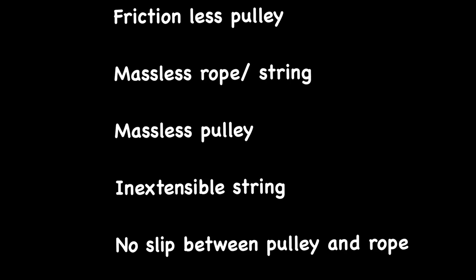That means the tension is uniform across the string or across the cord until it sees the next disturbance or the next mass or the next pulley in a mass and pulley system. Then the implication of massless pulley, the last one to see, it tells you that on both sides the tension has to be the same, because I don't have a J, polar mass moment of inertia.